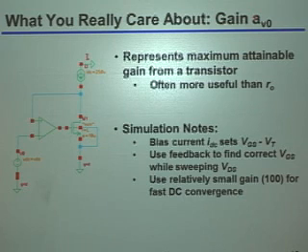Okay? And again, I claim that actually that intrinsic gain is usually more important than what the RO itself really is. Because it's not that you really know, like, oh yeah, I need a mega ohm of output resistance. It's more typically that you say, well, I need a gain of 10, 20, 30, whatever that number actually is. Okay?